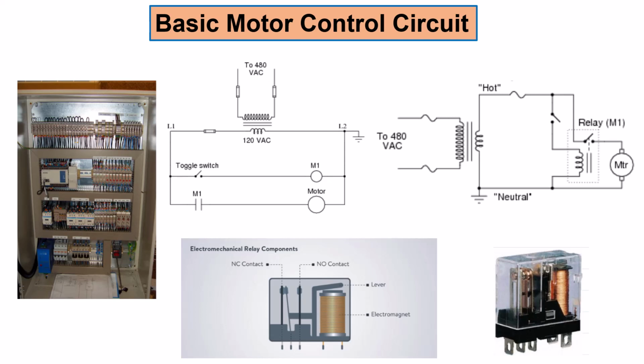So in this tutorial, I'm basically going to look at the difference between the two schematics here. This is a ladder diagram, okay? So this is a ladder diagram and this is a schematic diagram. What we have on my left is performing the same function as the one on the right, which is to control this motor. That's the function the two are performing, but they are wired differently, okay?